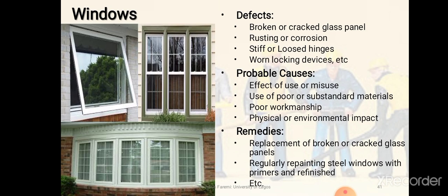Also, for hinges that become stiff, oiling or greasing of these hinges at regular intervals would minimize the rate at which the hinges get stiffened.